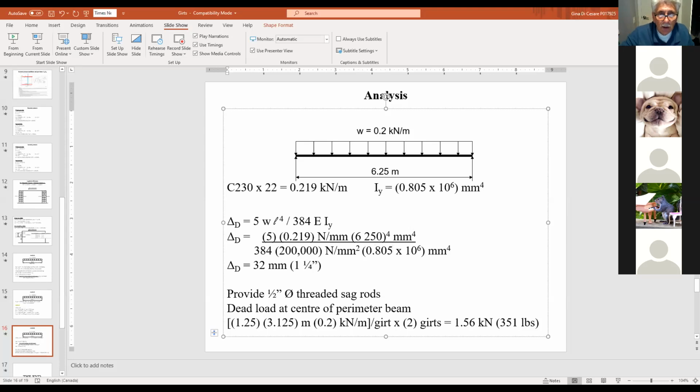Okay. See, Ramelin, this here means it's 22 kilograms per meter. That's the weight. Now you've got to convert it to a force. So if I take my 22 multiplied by gravity, 9.81, divided by 1,000, it should give you this answer. Is that what you get?